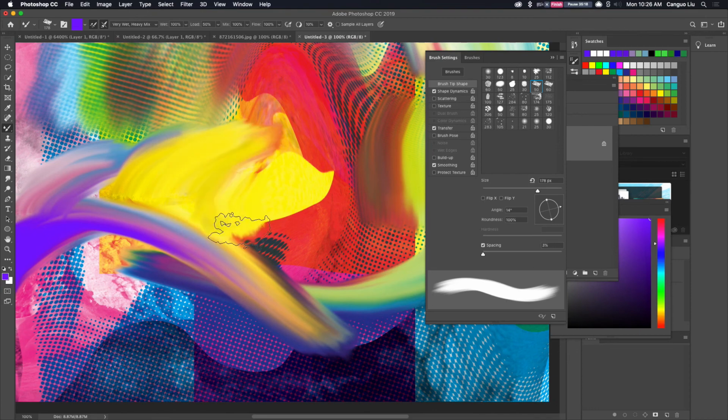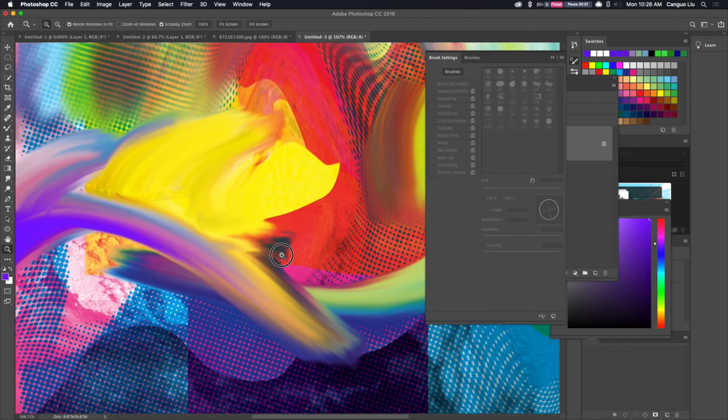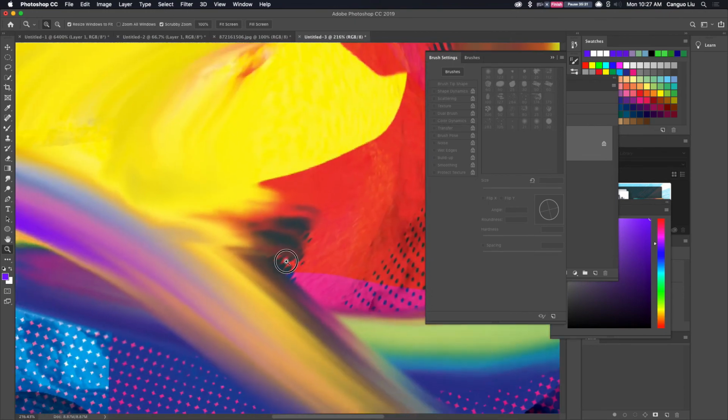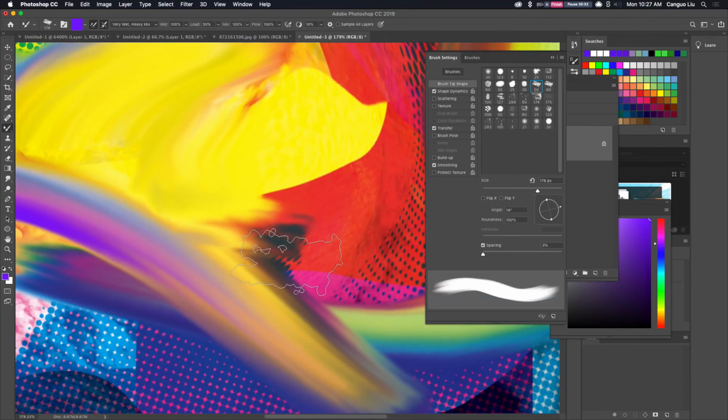You have the digital pen, so this is a nice time to do something with the pen display. Again, hit Z for zoom, hold Z and click and drag to zoom in and out. Hold Option and Control, click and drag left or right to change the brush size, and then you can draw.